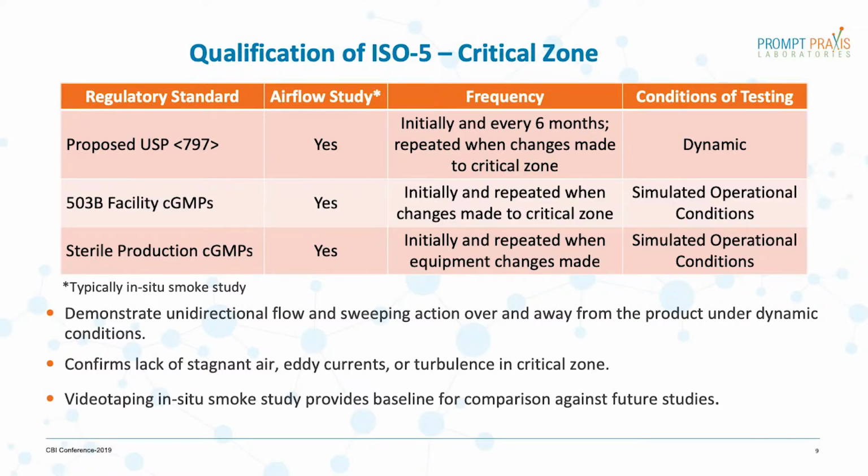And I've been involved in some where the agency really likes to see videotapes of your smoke studies. First of all, to verify you did it, and second of all, to really see that the room has been characterized properly, and it provides a baseline when you go to make changes to the room, introduce different equipment, that you're maintaining and still have the integrity of that smoke study, providing you the validation that they're looking for.